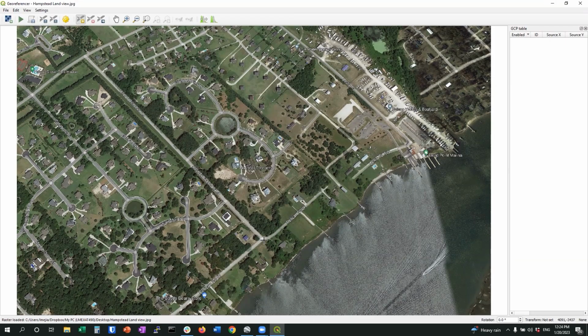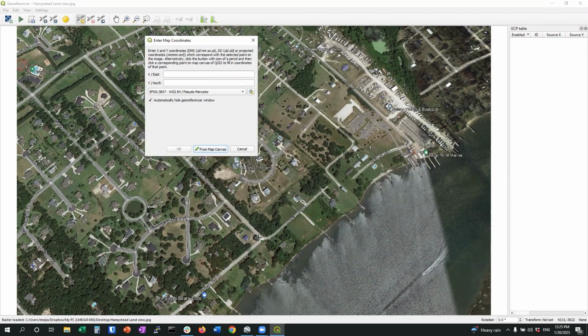But from here, once we have this, I'm going to try to find a good referencing point of my target area, because this requires a minimum of 10 points. So what you want to do is click on a specific point that you can find on the other piece of imagery. I don't necessarily go for the middle of the intersection, I go for the corner of the intersection. If I draw a straight line, yep, there's the sidewalk. Cool. If you know the coordinates for that specific area, you can go back and forth with Google Earth and it'll do it for you.